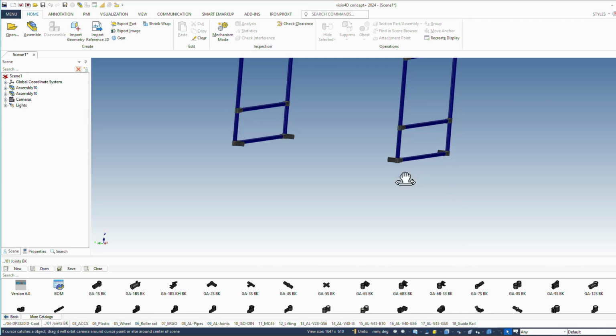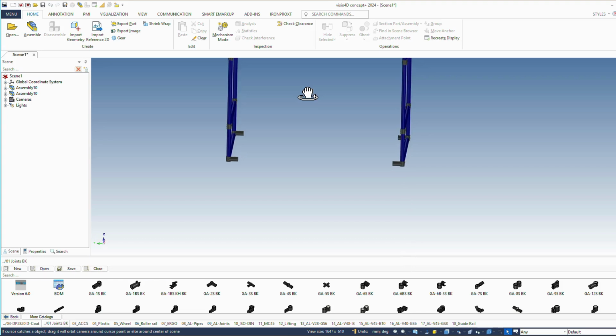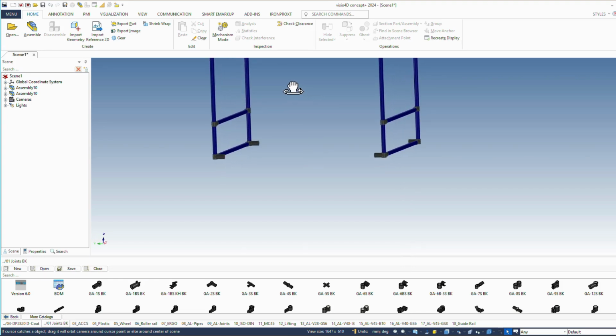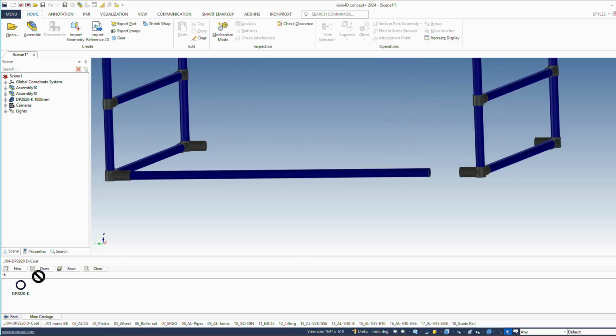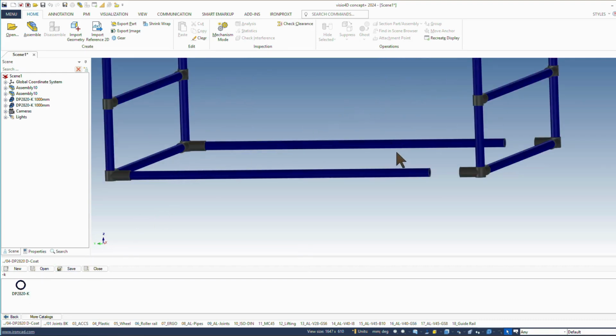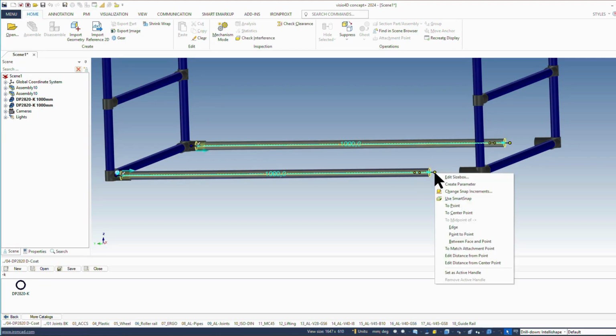Next, I'll bring the pipes back in again. That means I'll select the pipes here and here. I can use the Alt key to access the length adjustment, but I'll use the Shift key to add a second pipe. That means Alt key for one pipe, then press the Shift key as well. Hold down Alt and Shift, then add the second pipe. Both are now selected, and the length adjustment point is active for both.